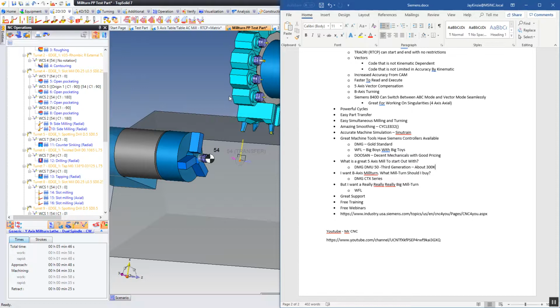The end result of this is better surface finish, but you also can take bigger cuts and just have higher cutting tool performance. So you can take the same tool and just get more out of it by suppressing that chatter and keeping that tool in the cut without having it bounce all over the place. And that would also improve tool life.